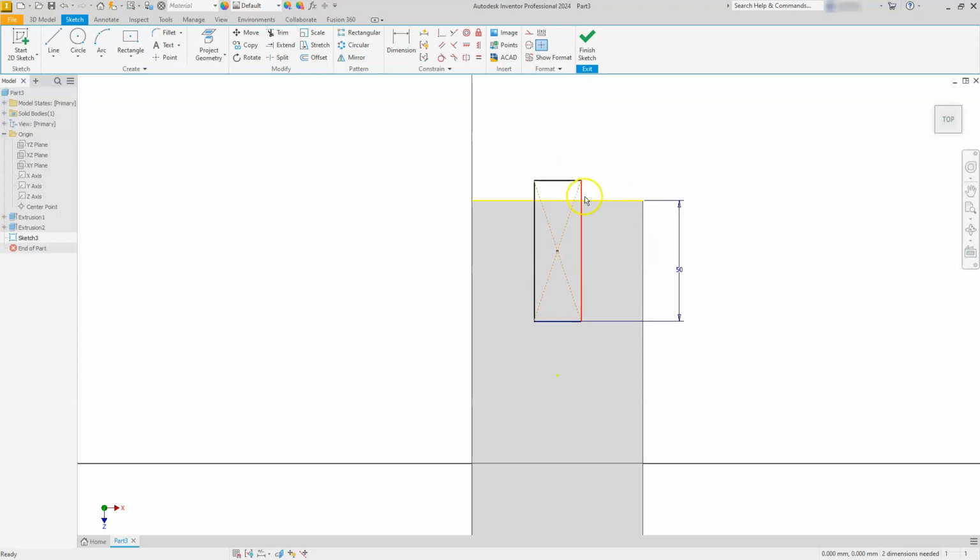I'm going to make this line collinear to this line by selecting a Colinear constraint, selecting this line, and then this yellow line. Create a circle. Let's click on this midpoint. And then I'm just going to go to that endpoint that's located here. So just 2 left clicks on that. I'm going to select this line here, make it construction.